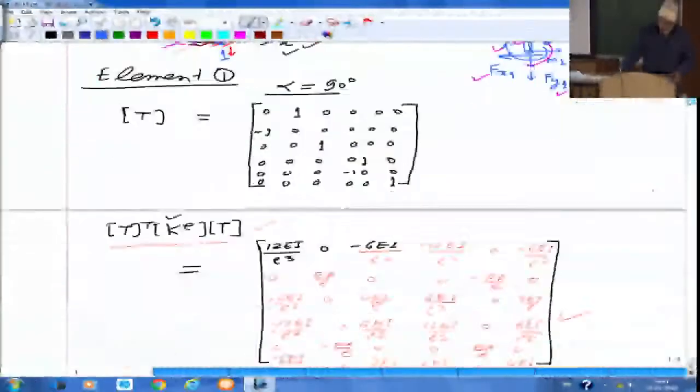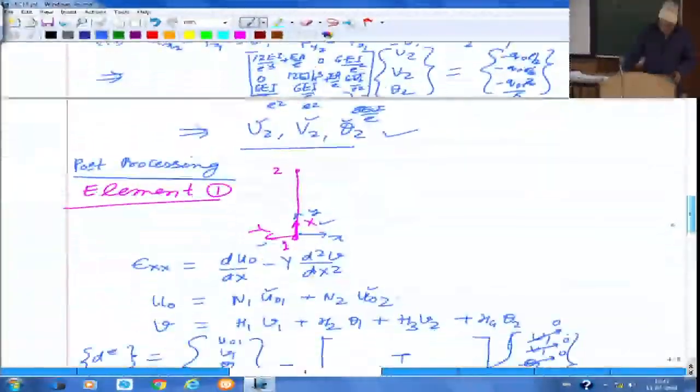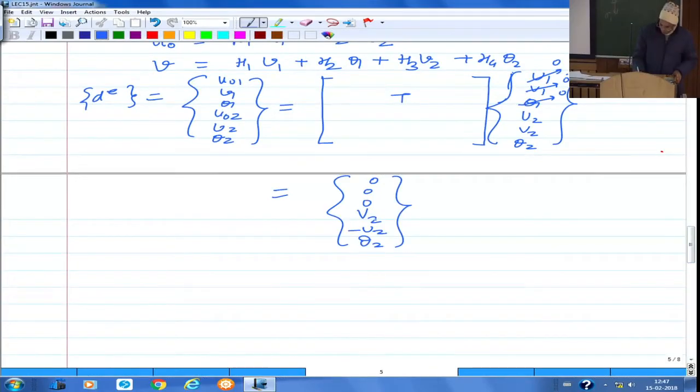That is what you see here, that for the second node, the local displacement is equal to the global y displacement, whereas the local y-axis is along the negative global x-axis. So the local displacement along the y direction is equal to negative times the displacement along the global x direction. You follow this? Although it comes directly from the matrix multiplication, you can also interpret these physically.